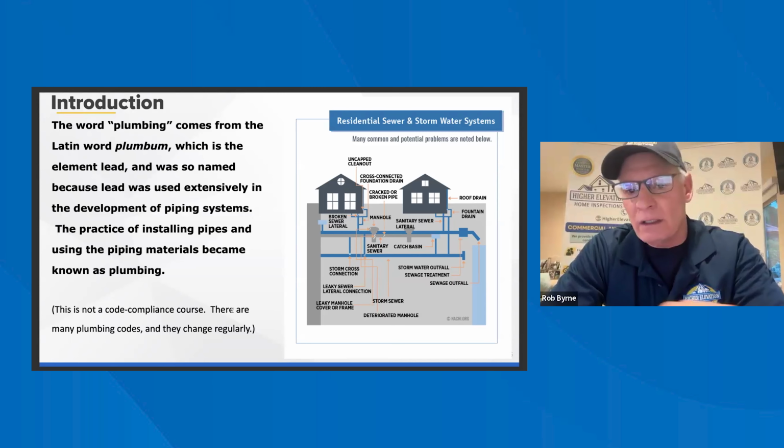When we come up to the toilet, when these are in the way, we move them, but we always push against the toilet to see if it's loose. We also want to see if they've caulked all the way around the toilet. We don't want to see them caulk the whole thing because if the wax seal leaks, we want to see it come out. Since this is the basement bathroom, and it's on concrete, they allow you to caulk it all. So our hot water's hot, cold's cold. So we're gonna let it run and see what we have for leaks.